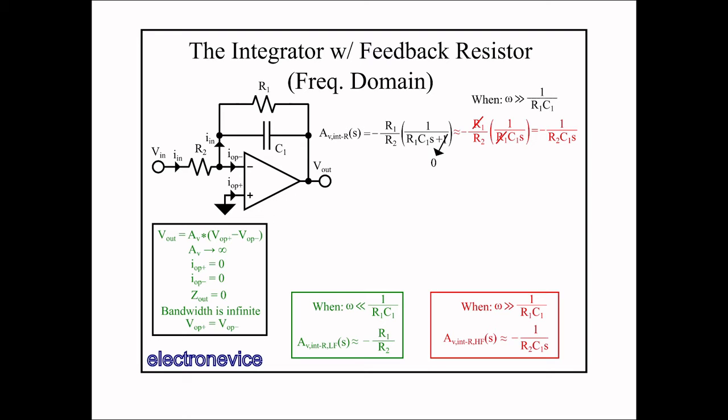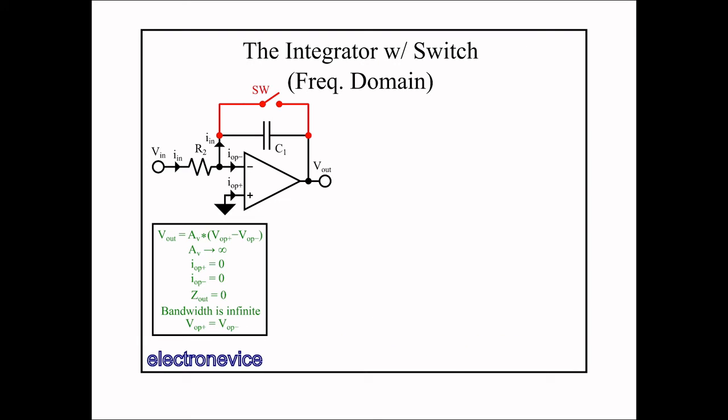So we can see here that if you only need the integrator to work for a certain frequency band, and don't need it to be particularly high gain at low frequencies, you can set the values for C1 and R1 to create two regions of operation, one at low frequencies that has a constant finite gain, and one at high frequencies that acts as an integrator. This limits the degree to which low frequency effects can change the output voltage, and permits the integrator to produce more practical output voltages.